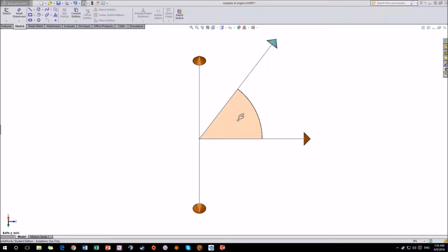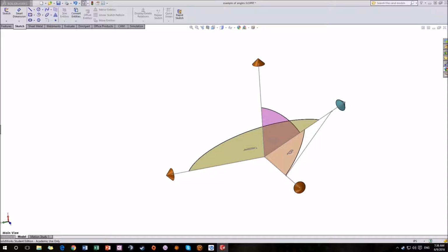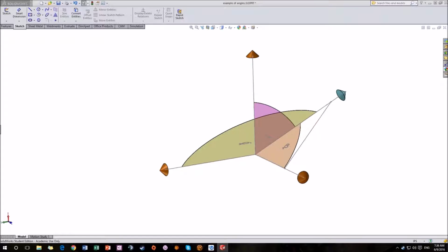If we connect a line from the force to the y-axis like this, we can see a right triangle. With this right triangle, we are only really interested in the adjacent leg of the triangle. So we can find that adjacent leg if we were to take the cosine of beta with the hypotenuse, which is the force.